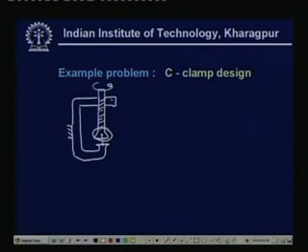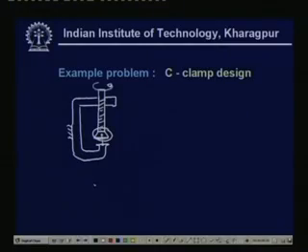Now, you see, whenever we want to give a pressure, we have to turn this screw and the whole body turns, but we do not want this surface to turn so abruptly. So, we need to stop this turning motion when it gets transferred to here, and this is done by means of what is known as a collar or thrust collar. So, this is a kind of thrust bearing which we use here, and the detailed picture will be, if you consider this to be the clamp,